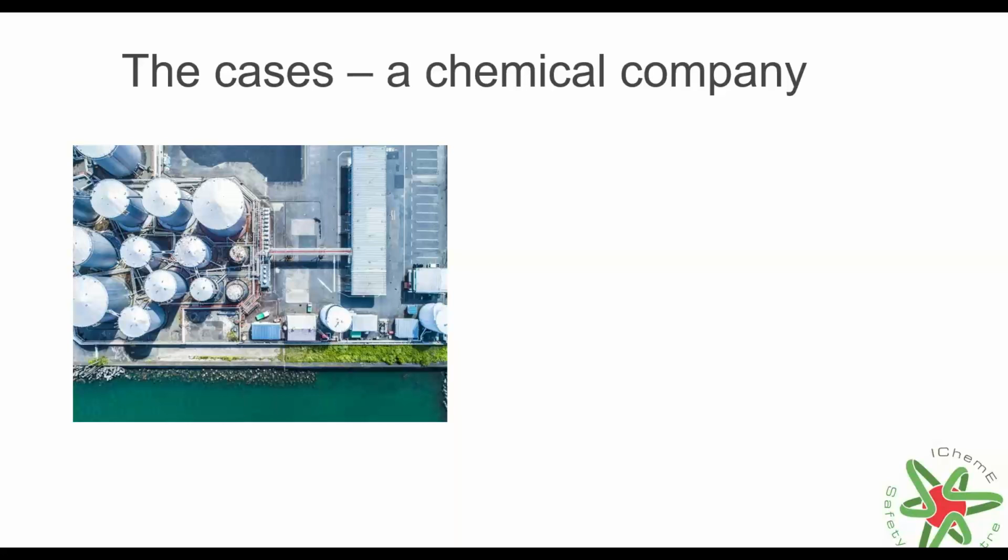The initial work was done while the slurry tanks were isolated and out of service. However, the actual final welding work was delayed because of material availability. So when the work recommenced, Tank 1 remained out of service, but the isolations to Tank 1 had been removed. There was also a vent line that connected the vapour space for Tanks 1, 2 and 3 that was never isolated. When Tanks 2 and 3 were returned to service, vapour migrated to the Tank 1 vapour space. This connection provided the pathway for the flammable vapour to be present in the tank being worked on.